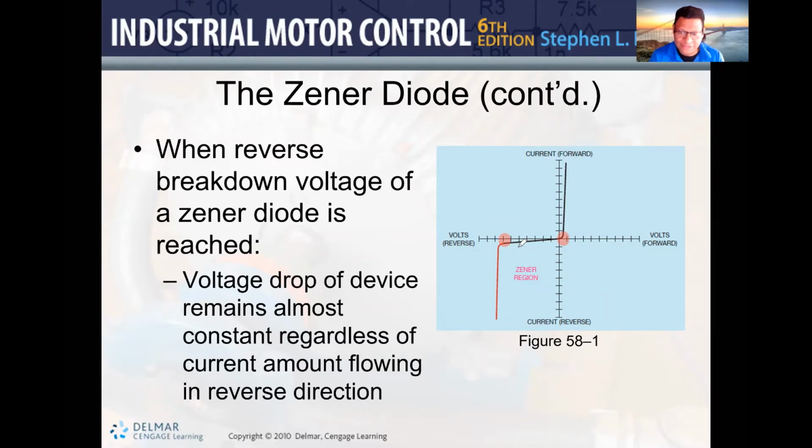as a dead short, or as a complete closed circuit, because it doesn't have the ability to continue to block the inverse voltage. Like in the case of the Zener diode, when the Zener diode reaches this region where it goes to its max reverse voltage, then the diode starts to conduct current. And once the diode starts to conduct the current, it's going to allow any increase in current. Number one, it's not going to burn out the diode, and it's going to cause anything which is connected in parallel with that diode to have the same amount of voltage drop that the diode has.